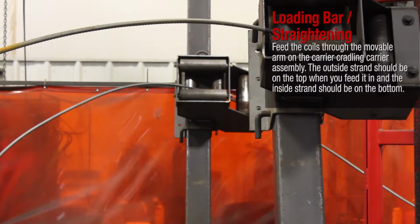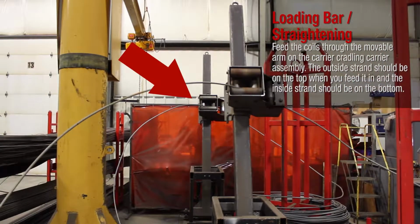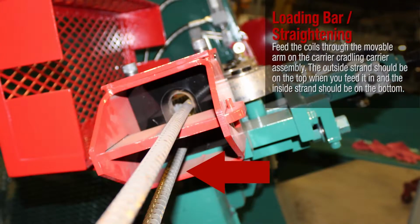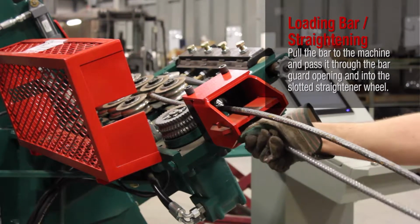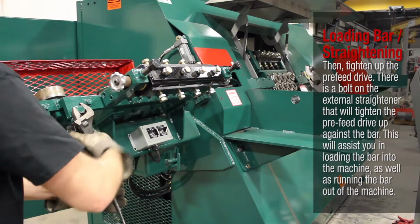Feed the coils through the movable arm on the carrier and cradle assembly. The outside strand should be on the top when you feed it in, and the inside strand should be on the bottom. Pull the bar to the machine and pass it through the bar guard opening and into the slotted straightener wheel. Then tighten up the pre-feed drive.